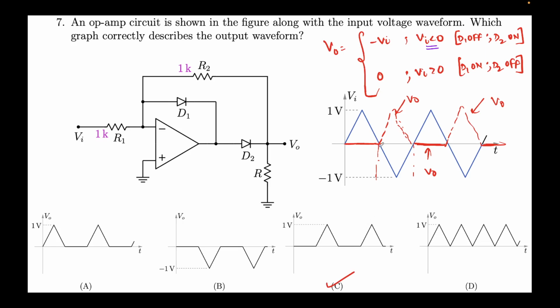Now just to summarize, this was a problem given to us with two diodes. We took all the four cases, right, where one is off, the other is on, and we solved. We applied KCL here, we applied KCL here. Using KCL, we saw that when they were on, the current should be positive, right, because they only conduct in this direction, for instance, and this one in this. And when they're reverse biased, their P minus N voltages should be negative. So if this is reverse biased, the voltage here minus the voltage here should be negative, only then it will be reverse biased. Using all those conditions, we saw that only two cases survived, which are these, and we obtained these results for them, which we have plotted for option C.